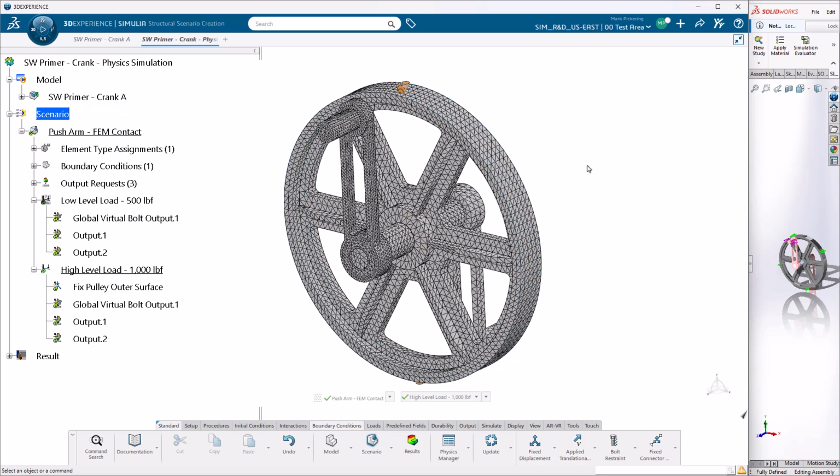However, there is one additional aspect that we have to consider, which didn't come up in SOLIDWORKS. Because we have multiple steps in this analysis case, which step did this boundary condition get applied in? Well, it is the active step. This can be seen in the feature tree as the step which isn't grayed out and has an underline emphasis.